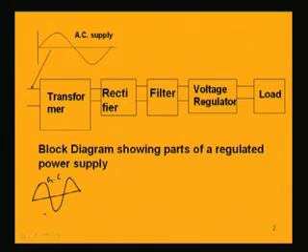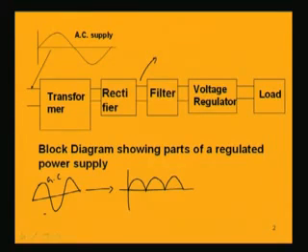So if I use a full wave rectifier, after the transformer steps down this input voltage to its bearable level, it will be rectified. If I use a full wave rectifier, I will be getting this type of output voltage which is rectified in both the halves. So after this rectifier, here we will be getting this type of pulsating DC voltage. This is called pulsating DC because it is not purely DC, but we have to get a DC which is constant voltage from this pulsating DC.